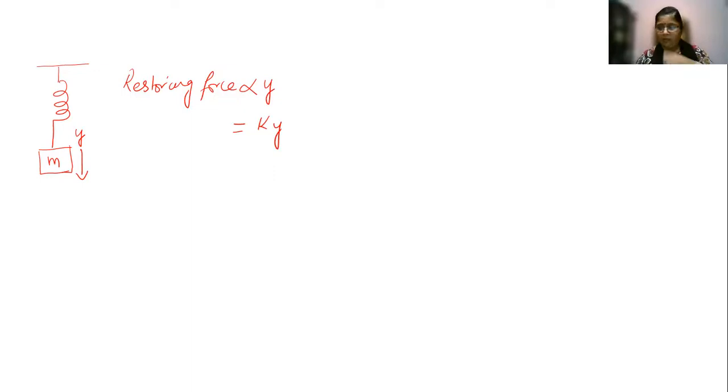Stop. Or you call it what is known as a damping force. This is known as a damping force. So what does this damping force do? Damping force just tries to stop you and is dependent on the velocity of the spring. So damping force is proportional to velocity. Or you could say damping force is equal to B into V, where B is the damping constant.